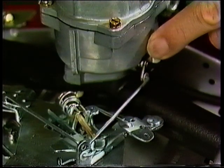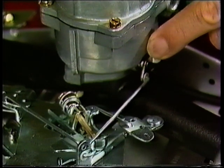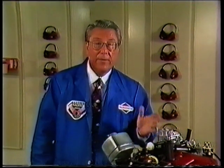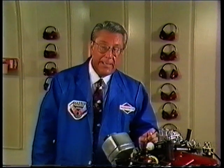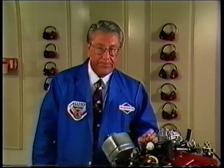If the engine hunts and surges only at true idle, when the linkage is against the idle stop, as shown here, you know you don't have a governor problem. Why? Because at true idle, the governor has no effect on the engine's operation. If there's no problem at true idle, you'll want to check next for hunting and surging at governed idle speed.